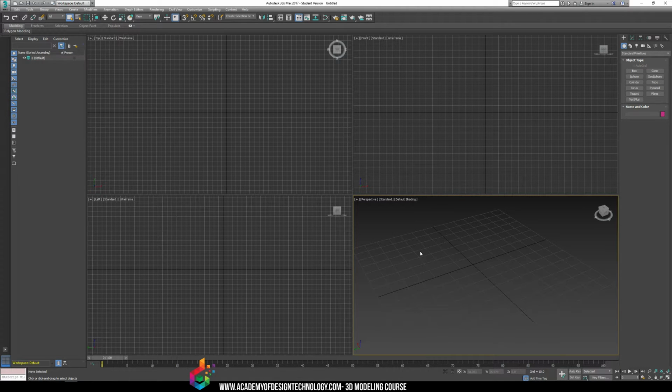So now that we played around with the camera a bit, we kind of know the camera keys, we need to start creating objects in 3D Studio Max. This is going to be a basic shape creation tutorial. What we want to do first is start creating a box shape inside 3D Studio Max. To do that, we're going to look at our command panel. I'm going to reset my scene here. I'm going to push Z on the keyboard. Don't forget that key as well. Z is for zoom extents, which will reset my view to focus on the middle pivot point.